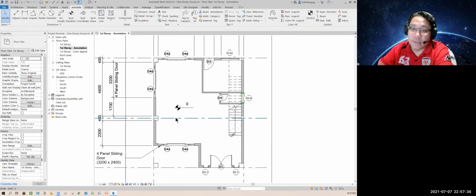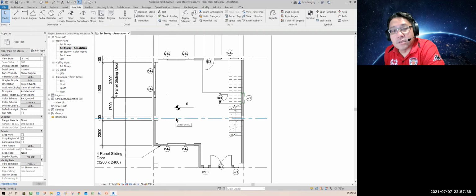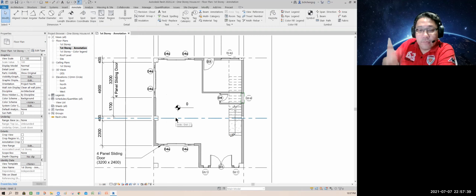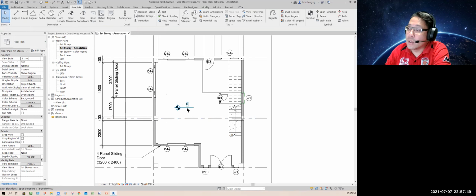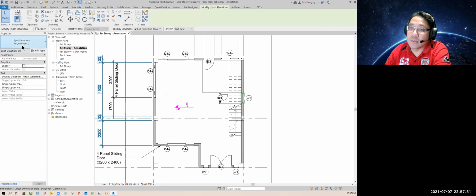Done. Now, why 0? You might ask yourself, hey Bernard, the elevation we raised up already, what? Yeah, we did that. But why is this still showing me this? It's very simple. Because when I select this, it is based on project base. So in other words, we have to create one called survey.